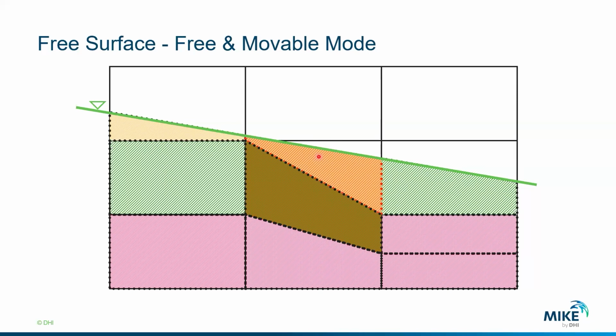The advantage is that it is very fast to solve in cases where you are simulating very large regional models where you are not much interested in looking at the details in the unsaturated zone. Then the method is nice because it will ignore the unsaturated zones and then it will solve and give you a major distribution of the water table.